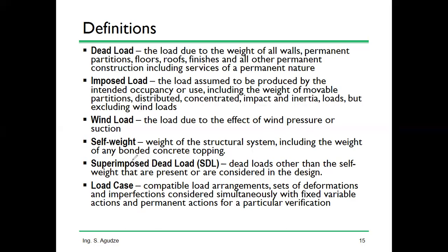But when it comes to superimposed dead load, for example, if you take a slab, the slab is the structural element. But we do screeding, we lay tile, so the screeding, the tiling, the terrazzo finish, and all that, they are what we call the superimposed dead load. The plastering and so forth, the ceiling.